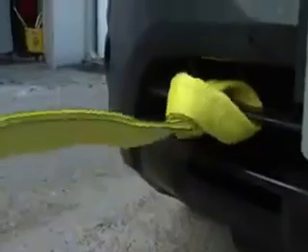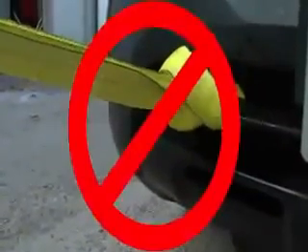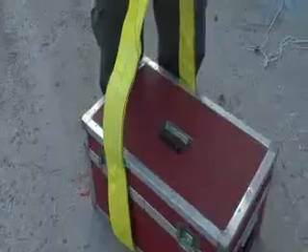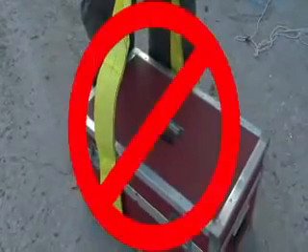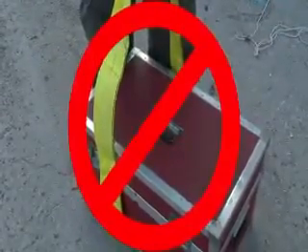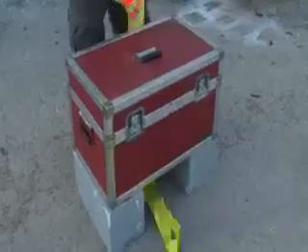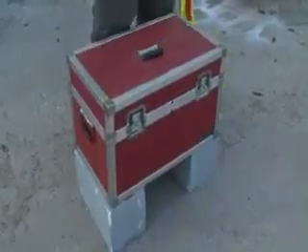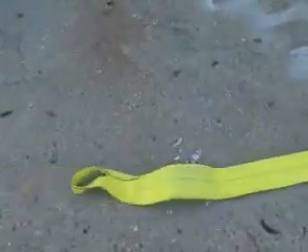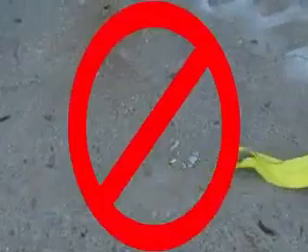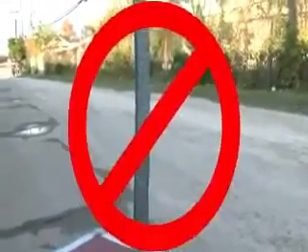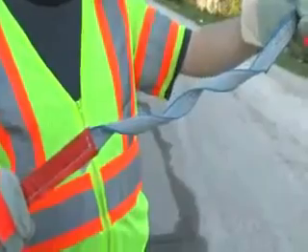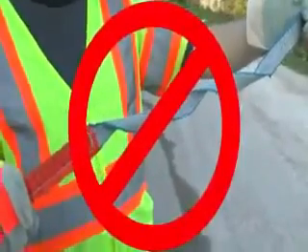Slings are only for vertical lifts. Never drag a load horizontally. Do not rest loads on the sling. If a sling is under a load, do not pull the sling out. Reset the load to remove the sling. Do not drag slings on the ground, the floor, or over abrasive surfaces. Do not allow shock loading. And always avoid twisting and kinking of a sling.